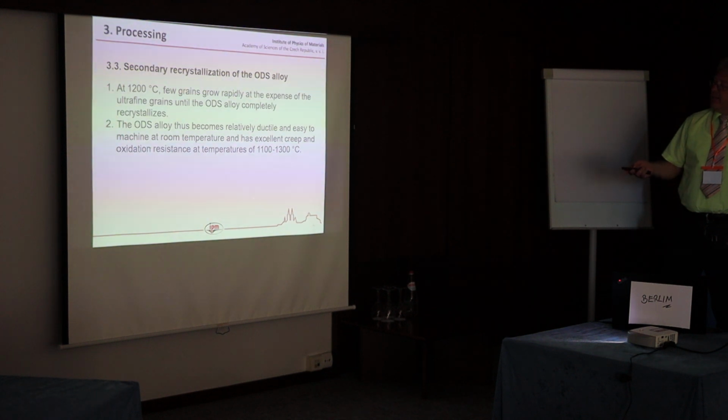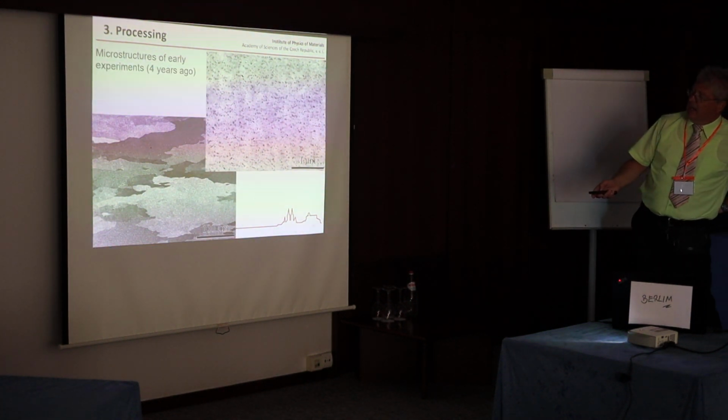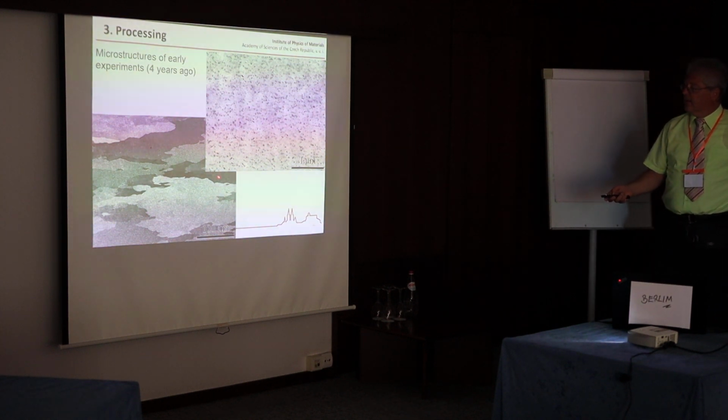The ODS, it's not easy to recrystallize it completely, but there are ways. The ODS alloy then becomes relatively ductile and easy to machine as practically normal steel at room temperature, and it has an excellent creep and oxidation resistance at these very high temperatures.